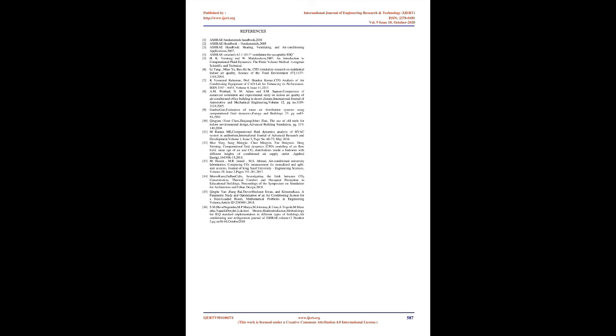Also after the end of 120 minutes it soon crossed the 5000 ppm mark, which is the hazardous limit. Temperature contours show that there are some low temperature pockets, and velocity contours show the velocity near human foot and head is high, the combined effect of which may cause local discomfort in those regions. Also by observing the velocity contour it can be seen that ample spots are there in the laboratory which have close to zero velocity, which shows that air is stagnant there, so such zones have high CO2 concentration. So the air distribution should be designed in order to reduce such zones.